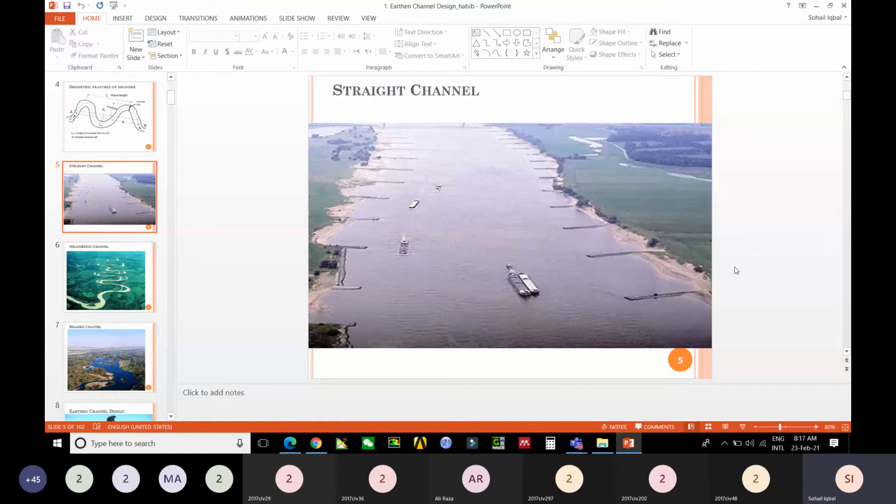A student says: to reduce the velocity of the water, for water training. Yes, water velocity, definitely. These are water training structures. If you have studied about these, you can also tell about other plus points. There must be some other benefit, not only that these are river training structures. These are also provided to save the embankments from erosion.